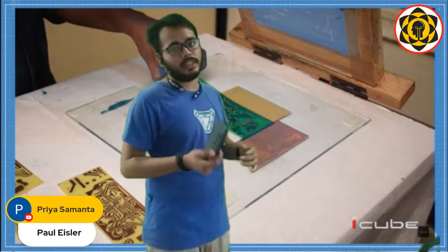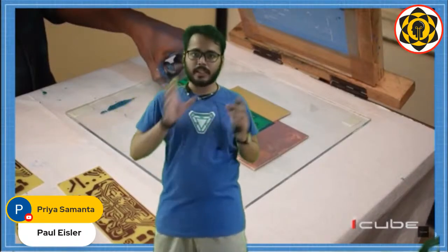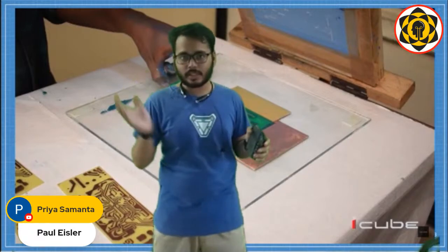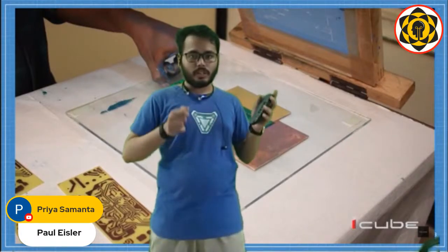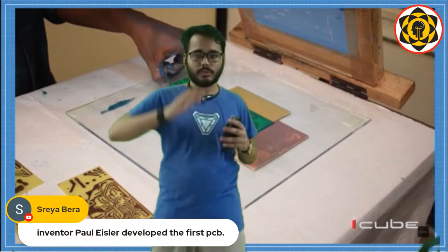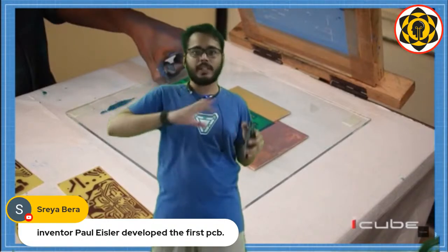Now you guys might ask why I didn't do the legend on top of the masking so that it gets more visible. See, masking is a more durable paint than the white legend paint we are using. So if we do the legend below the masking, it will give it more durability in the long term, so the silk screen does not rub off. If the silk screen rubs off and the masking is still there, the PCB is basically useless, because any person will not understand what the holes are for, because he does not have the schematic. That's why we do the silk screen below the masking, because the masking is the most heavy duty paint among all of this.